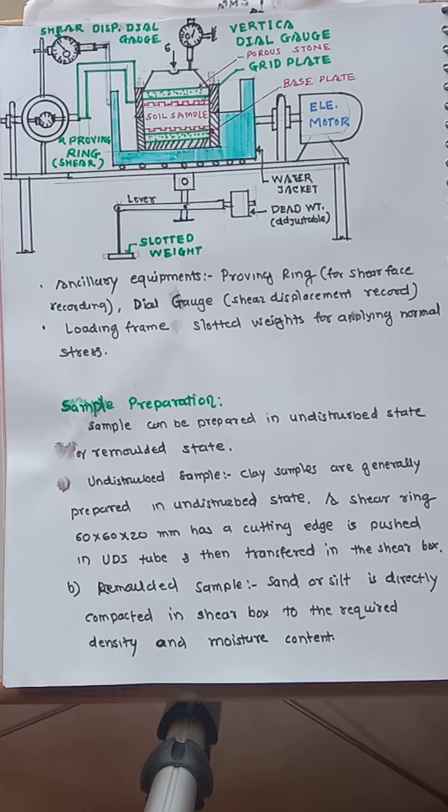Okay, so a chart is available called a calibration chart, which gives the incremental load, like 1 kilonewton, and the deflection in the ring recorded by this. Okay, suppose 20 units, then 2 kilonewton, say 25 units. Okay, so this chart is available.